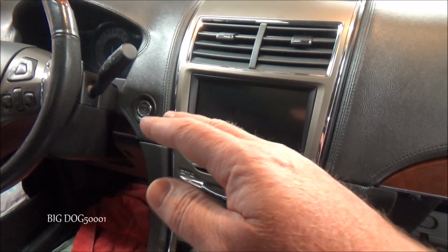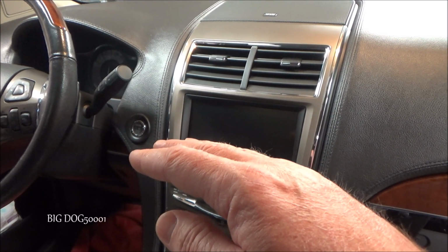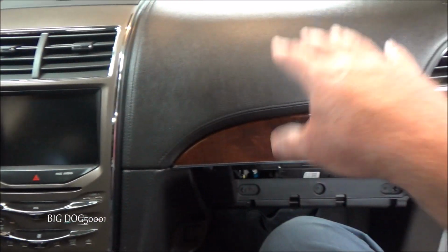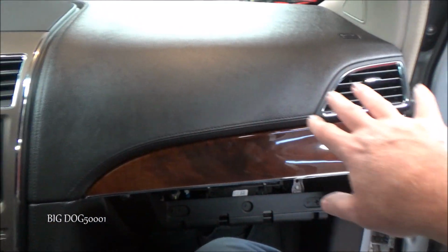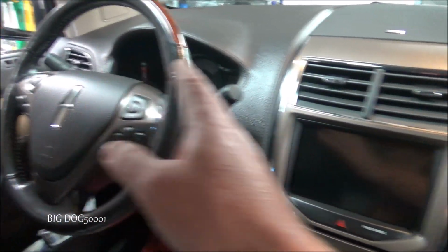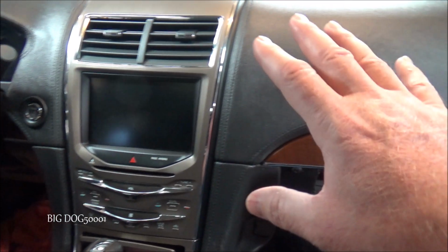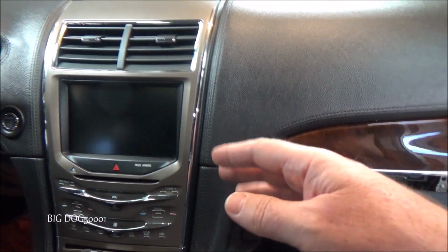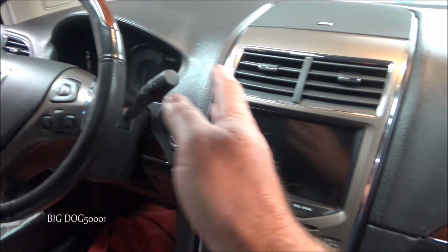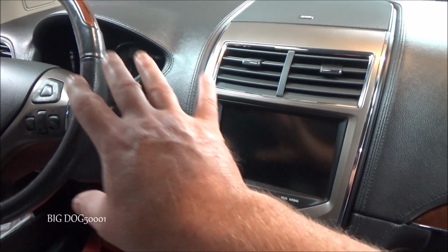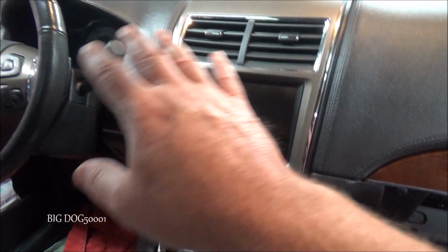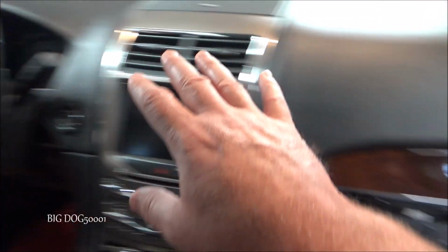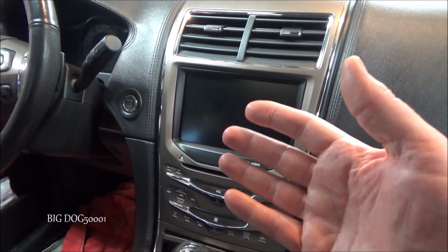In the case of a Honda with a low refrigerant issue, just the way it's plumbed, the refrigerant comes in on the passenger side and runs through our evaporator core. It's going to cool this side first, and then cool this side second, just the way the refrigerant travels. So if it's low on refrigerant, and I did a video on this before, by the time the refrigerant gets over to the driver's side, it will have lost its capacity to exchange that heat. So you're going to feel warmer air over here than over here. That's why, if I see heat over here and cool over here in a Honda, I'm looking toward a refrigerant issue.